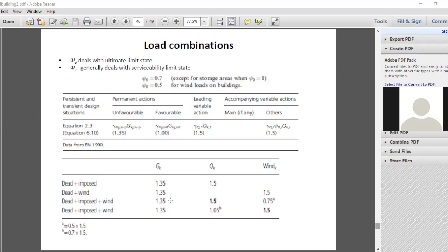But most of the loads, say 95 to 98% of the loads that you have anticipated, are now acting on the structure with respect to the permanent loads. So there can be a little room for adding few more loads, like the weight of finishers and so on, that are going to come in the last part of the building construction.